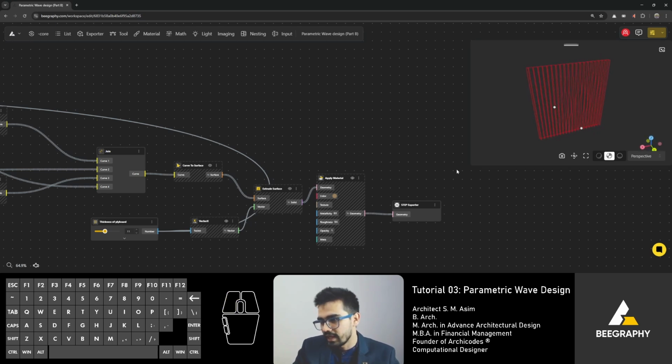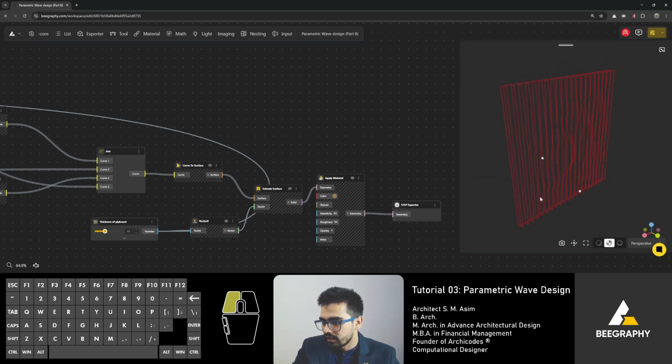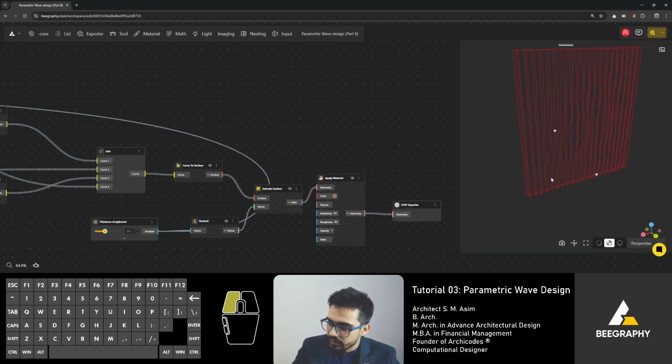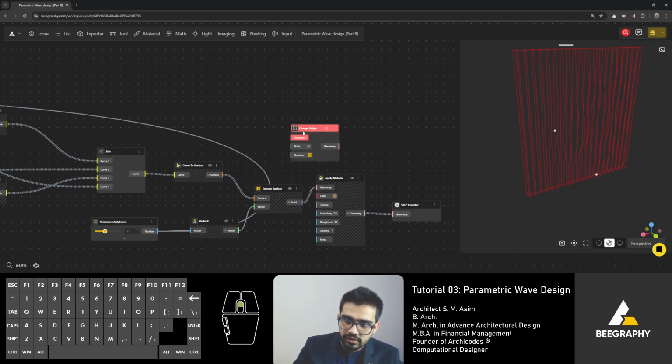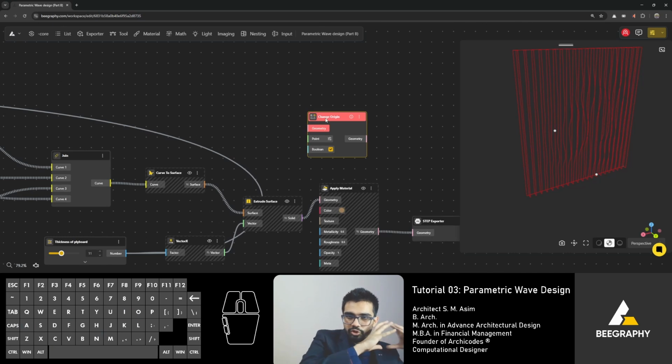What would this be? X. Wait. All right, so this is what we'll do. We are going to take all of these curves and put them at one point, and then we will simply rotate them. That will fix everything. So let's type in change origin. Change origin moves the geometries to a point, to any point that you like.